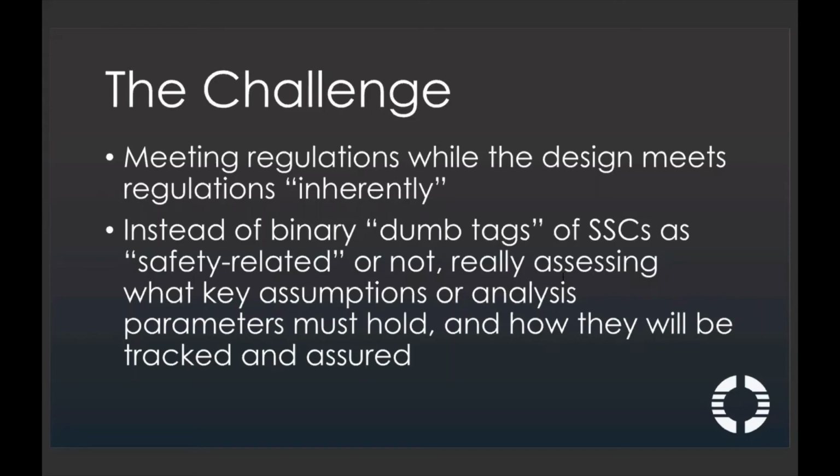And instead of essentially giving what I'd call binary dumb tags of SSCs as either safety-related or not, we're really assessing what key assumptions or parameters around those SSCs must hold, and how those parameters are tracked and assured. So we feel like this is a more holistic process to really ensuring that the safety we're talking about in these systems is actually ensured all the way through the process and even in operation.